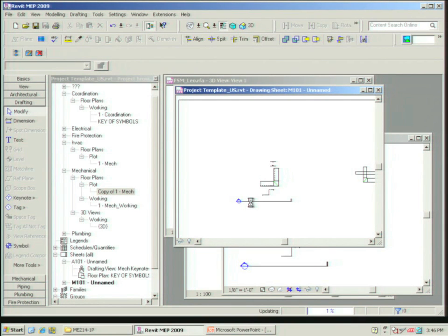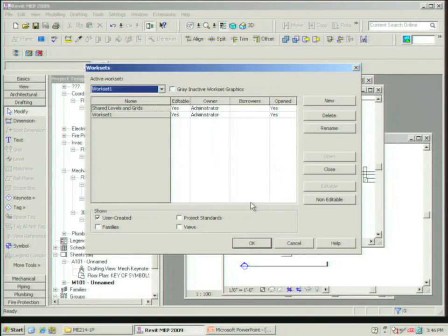And second thing is the control by view filter. In the same plan view, you will have a work set tab and a filter tab. What I will do is, let's say you work on an electrical, and obviously you don't want to see any piping or mechanical work on your electrical drawing. So first thing I would do is just turn off all the work sets, mechanical work set or the plumbing work set, in the first point. And creating those filters is a little tricky. You can create your filter by work set as well, but you're controlling that already. So you don't have to do that.